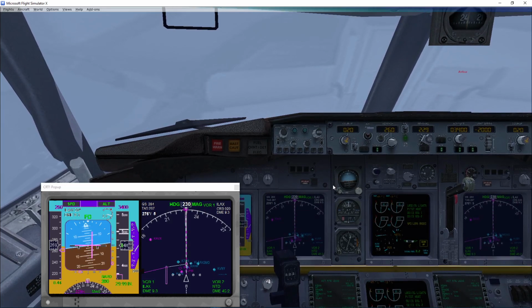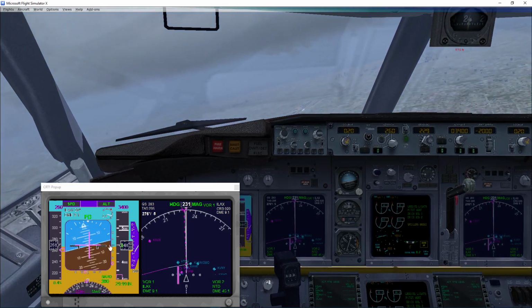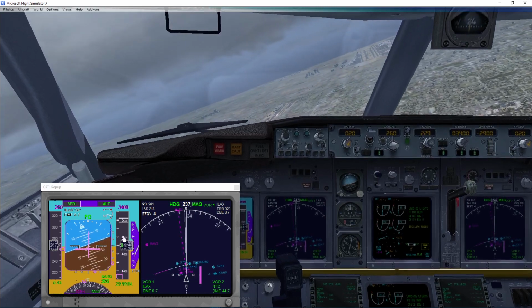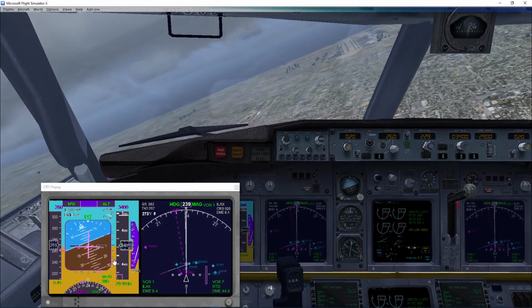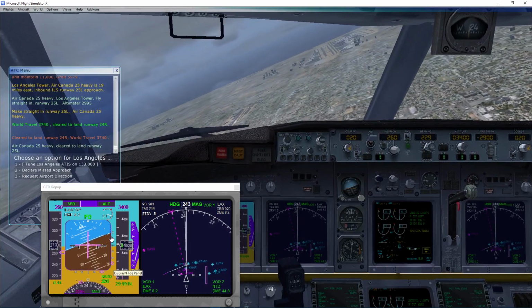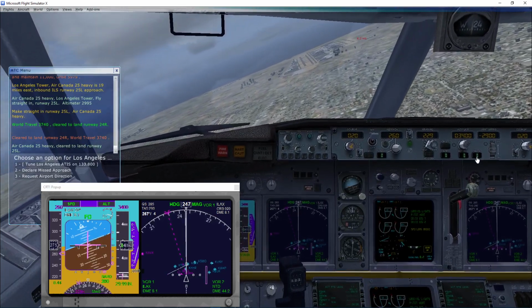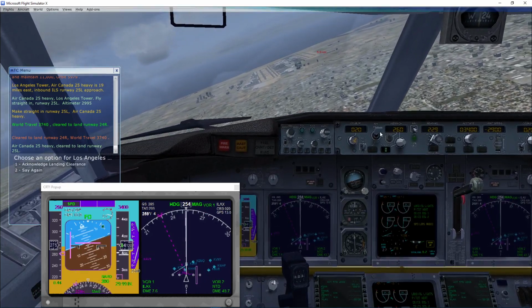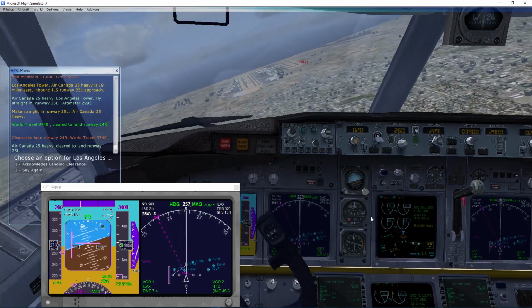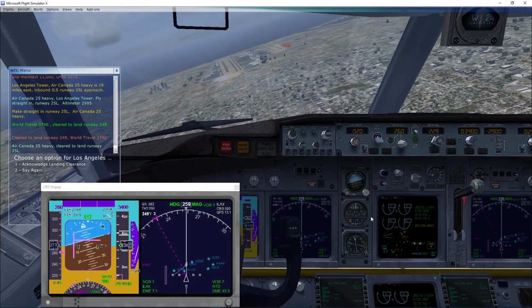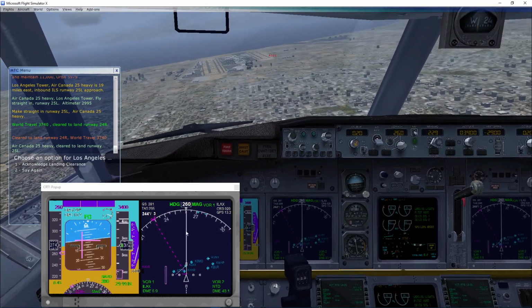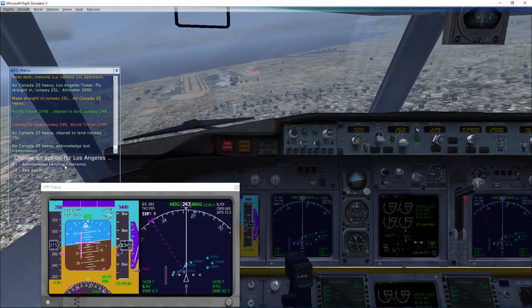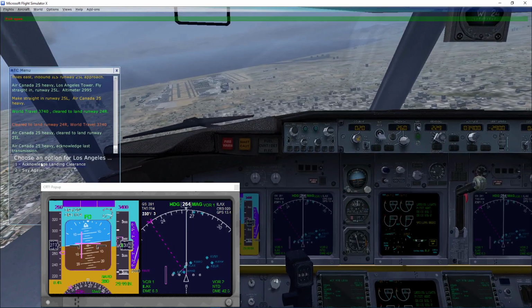Or not, we might have. Here it comes. I'm not seeing it there. We're way up above. We're too high above our vertical diamond. It should be up above us, and it ain't. So I'm gonna have to disable the autopilot. Start bringing it in manual. I believe it's that one, ain't it? You gotta come down. Well, I ain't got enough to.